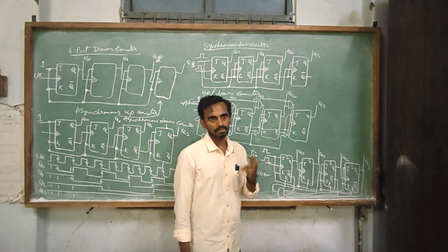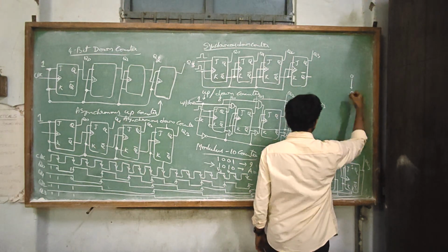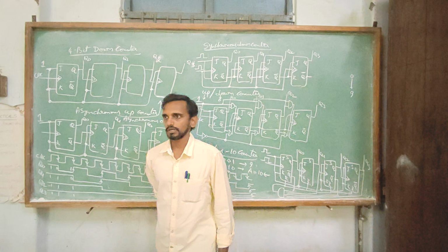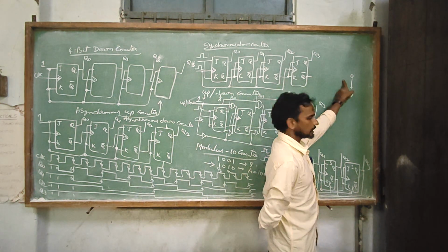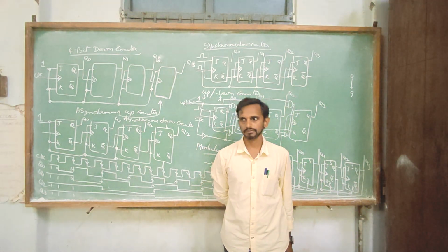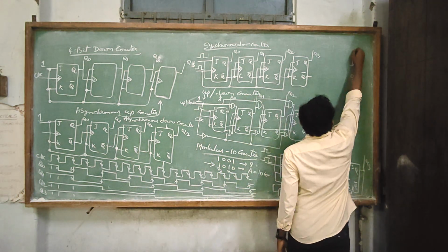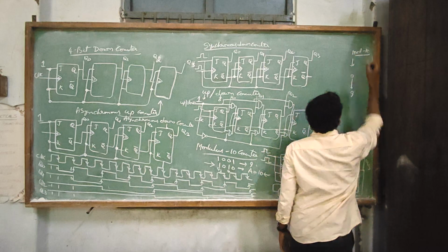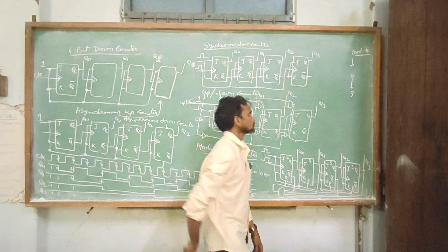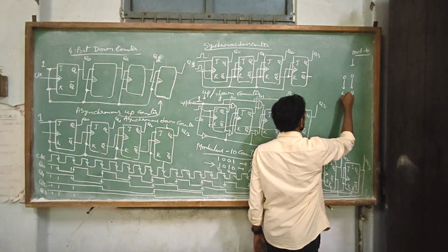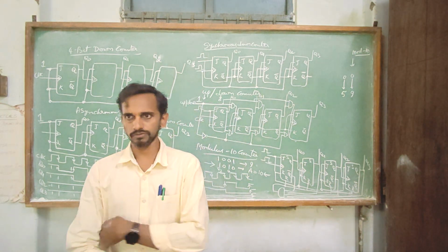For the seconds counter, the first digit will count from 0 to 9 and after counting 9 it will reset to 0 and the next digit increases, right? So here we have to use a mod 10 counter. And for the second digit, it has to go from 0 to 5, and after counting 59, the counter resets to 0, 59 seconds.